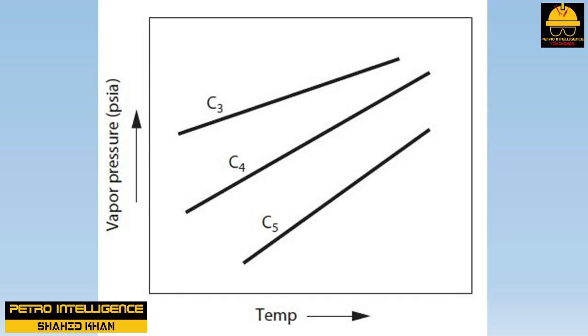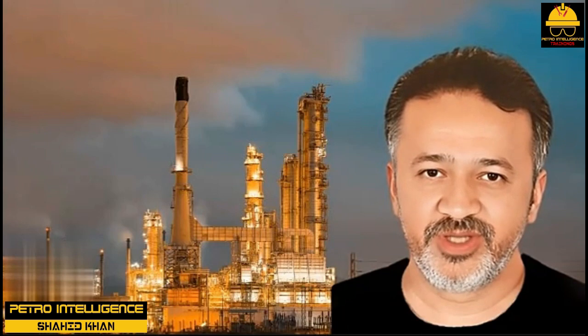The temperature and composition are called independent variables. The pressure in the drum could now be calculated from the chart in the picture. The pressure is a dependent variable. The phase rule for the reflux drum system states that we can select any two variables arbitrarily, temperature, pressure, or composition, but then the remaining variable is fixed.